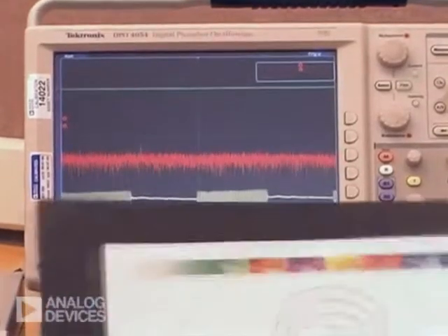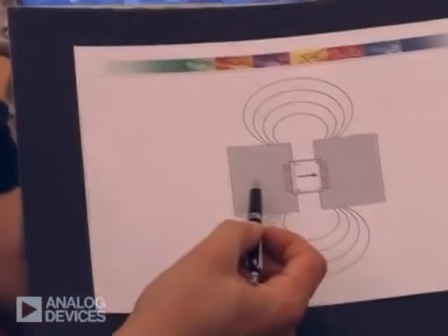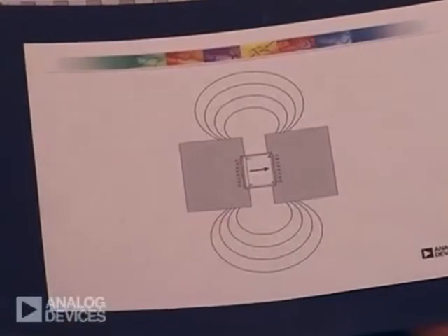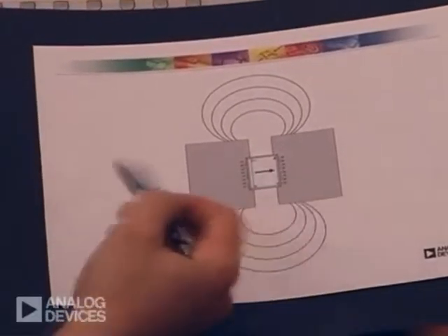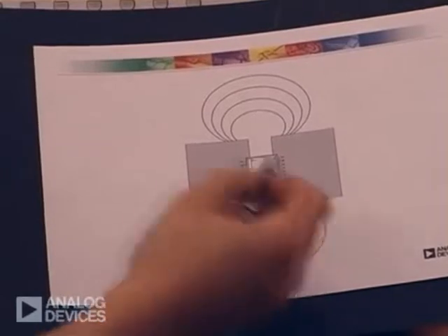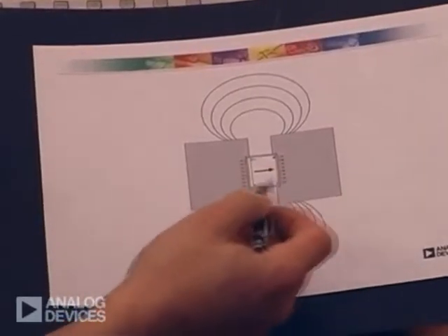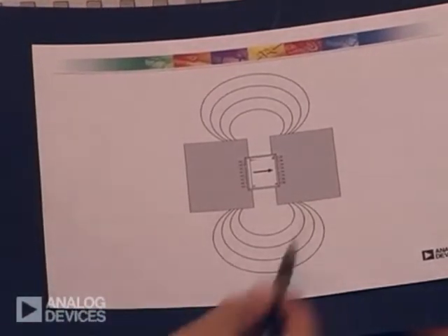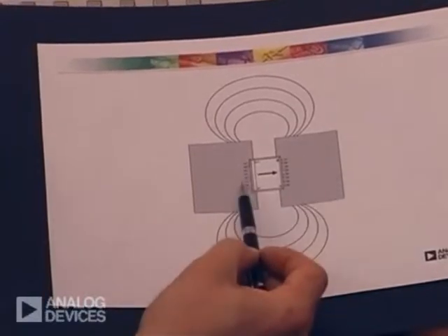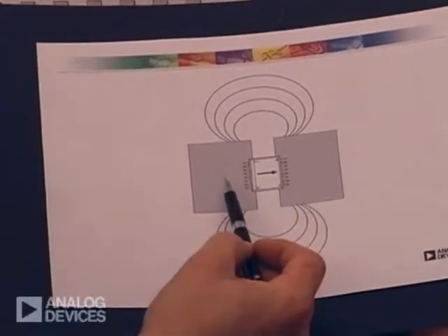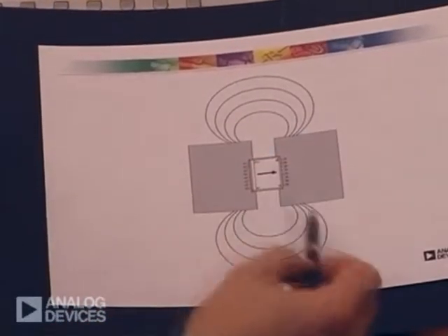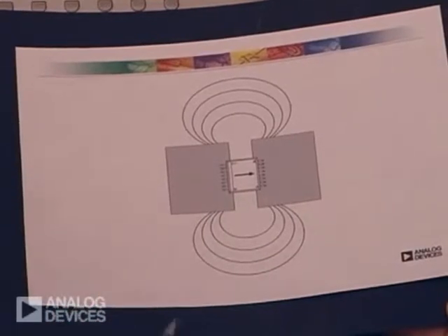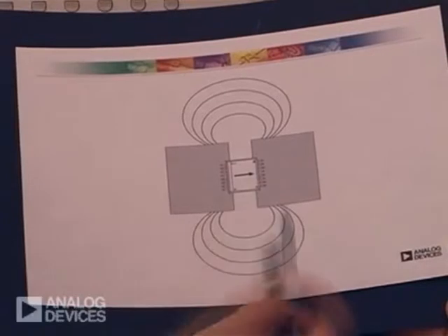Our other issue is that our part drives power from a primary side to the secondary side across a split in ground planes. From a DC point of view, this isn't a problem. Each side kind of works independently and hands power across fairly symmetrically, but at the frequencies that we're worried about, 180 megahertz and especially 360 megahertz, it generates differential voltages and currents across these ground planes, turning them into a fairly efficient dipole radiator. The best way that we've found to eliminate this kind of noise in the system is to short the dipole out.